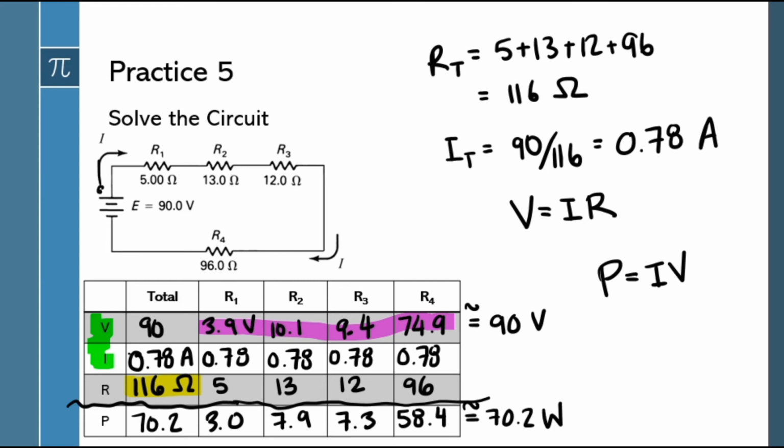So that shows us that, once again, power has that formula of addition. So PT equals P1 plus P2 and so on, no matter whether you're in series or you're in parallel. Now, if you check my numbers, you'll be like, you're off by 3 or 4 or 5. That's all because of rounding. So I went back and double checked. Just be careful, rounding really does change them, but the theory should be consistent.